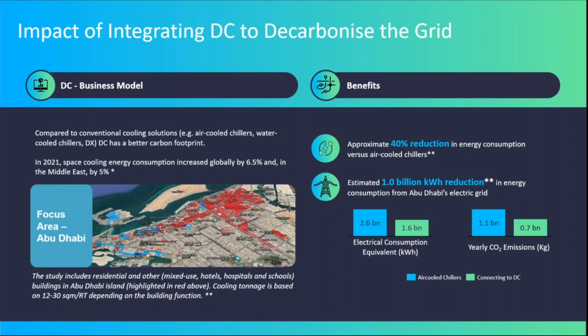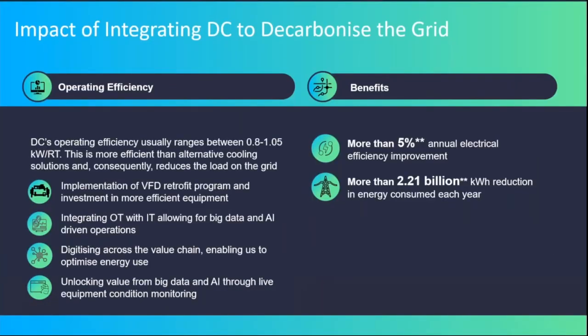Another example in the next slide, and here we focus more on operational efficiency and operational excellence. District cooling, as we saw before from our colleagues from Qatar Cool, showed improvement of energy efficiency during the year. So this is the global pattern that we are observing in all the region, with efficiency as low as 0.8 kilowatt of electricity per ton of refrigeration. This is also due to implementing different solutions and different optimizations in the system.